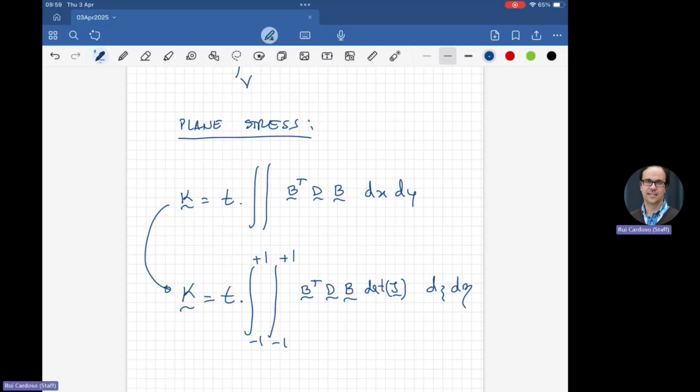And also to give you an idea that in a FEA code, you have many different types of elements, each with their own formulation, right? This mathematical formulation we are seeing here is to build the stiffness, to build the mass matrix, to build the internal force vector. So we already talked about stiffness. We introduced that with the strut element in previous weeks.